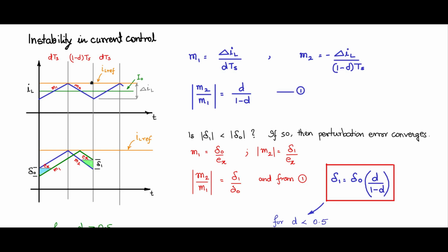So there is a solution for this. There is a standard solution for this, which we call slope compensation. Let us also discuss about that. The inductor current. I will draw the time versus inductor current, and I will keep the markings in such a way that the duty cycle is less than 0.5. I want to show few cycles. Now let us say this is one cycle, second cycle, third cycle, fourth cycle.